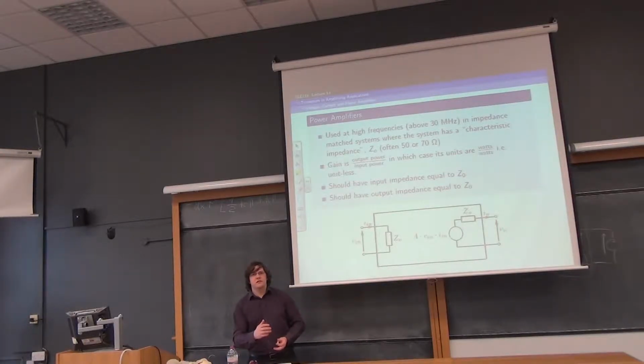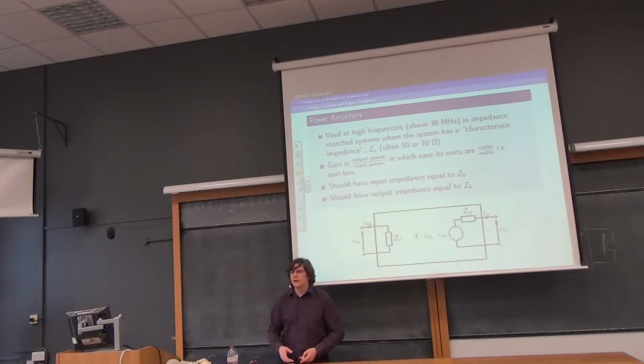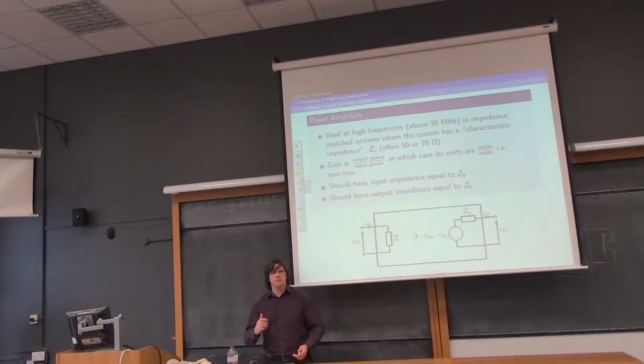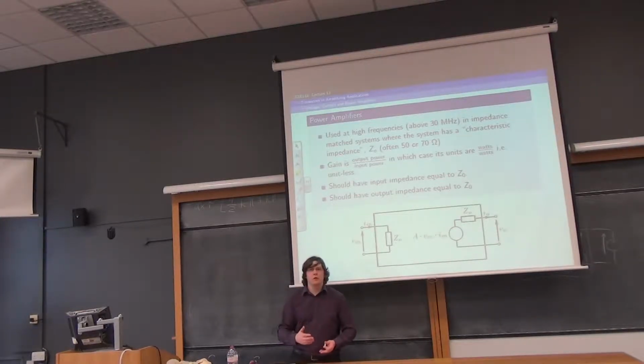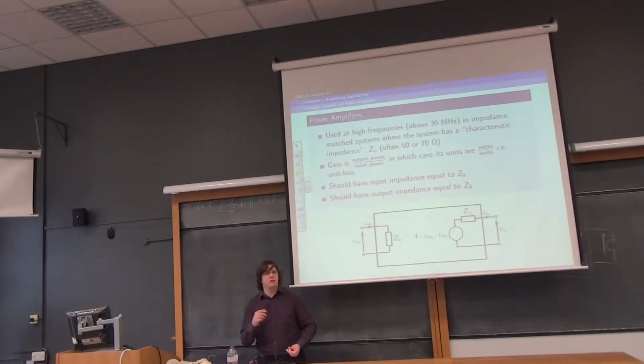It doesn't know anything, but it knows about the impedance behind it, looking back into the wires that it travelled through. And if they're not the same, that's like a mirror, or a badly silvered mirror. So there'll be a certain amount of reflection. When the impedance that it's coming from and the impedance that it's trying to get into are equal, there will be as much power delivery as we can manage. So that's an optimal situation.